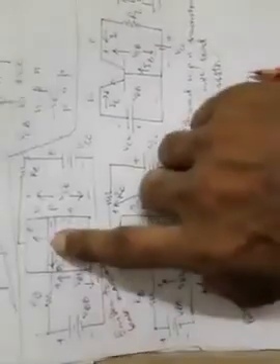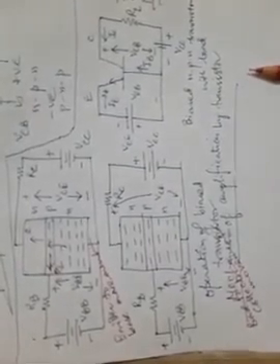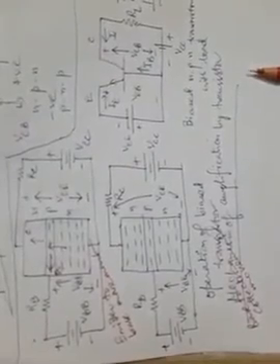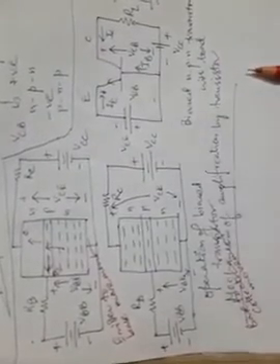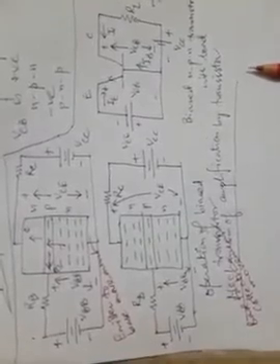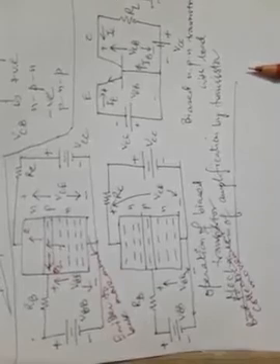The other reason is that since the base is lightly doped, that means the base is doped with majority carriers as holes, so the concentration of holes will not be that much higher as compared to the injected electrons from the emitter to the base area. Because of that, although there will be some recombinations, that recombination will not exist in a very high percentage.